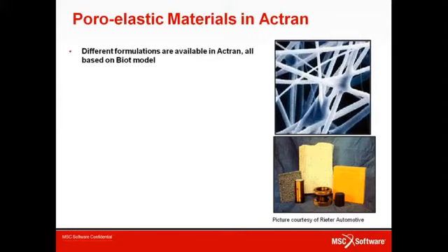Different formulations are available in Actran that are all based on the theory developed by Biot. This theory involves the characterization of a vibrating skeleton that interacts with a surrounding fluid in the pores, and this fluid is usually the air.